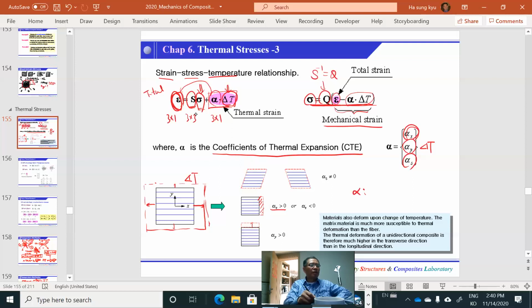So depending on this material property, we have free expansions in every direction. And importantly, in shear, alpha s is 0, mainly simply because of symmetry. If this is non-zero, positive, then the strain will be positive, but we can just rotate and switch, and this becomes negative.